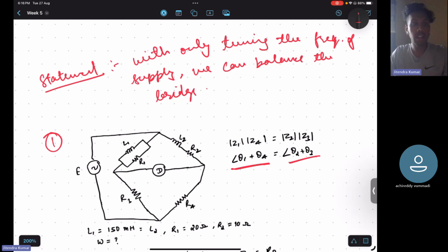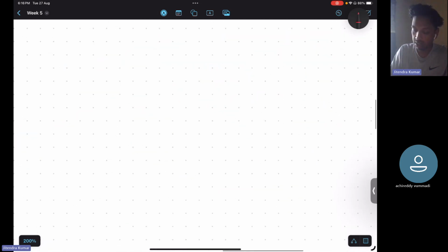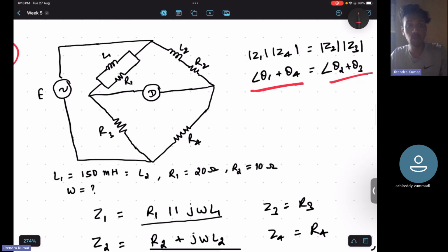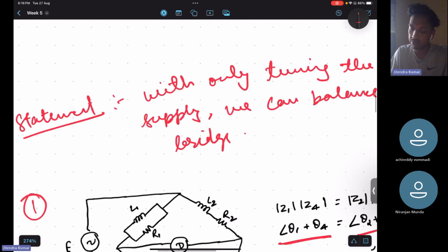Another logical reasoning question is like, the bridge can be balanced if the supply waveform is, so we have to tell on which supply waveform this bridge can be balanced. There are a couple of AC signals, we all know, like sinusoidal, the ideal kind of waveform. Then the square waveform, that is also an AC waveform. Then triangular waveform, or any periodic function, or half wave symmetric.